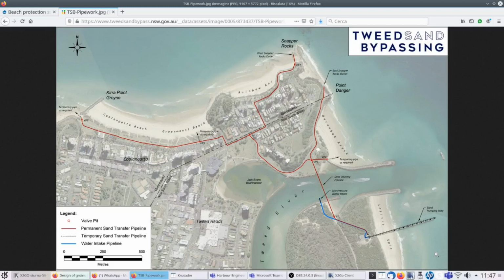So it is a solution that is frequently adopted, but the problem is that in doing that, you originate accretion of the beach. Accretion of the beach, in this case, in the bottom part of the figure, and you can clearly see that the beach in the bottom part before the walls goes into the ocean more with respect to the upper part of the beach, after the walls, where you don't have any more supply of sediment delivery.